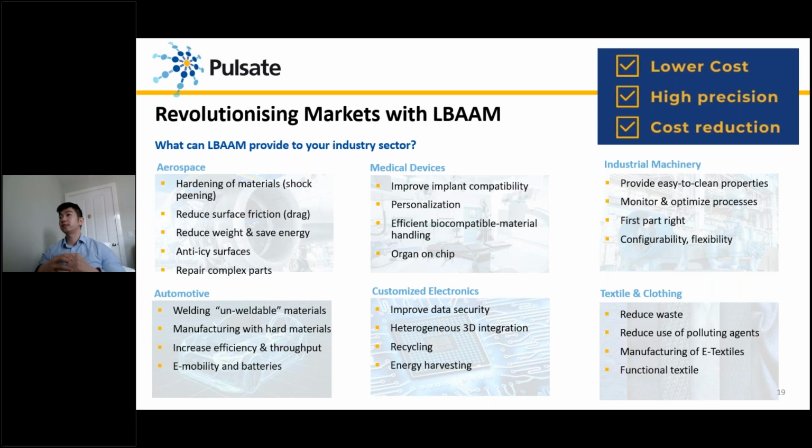So generally speaking, lasers can be used for either addition of materials or removal of materials. Those are the two main big categories. And under those two categories, you can go down to different processes. For example, for laser removal, you have cutting, drilling, texturing, laser cleaning, and for materials addition, you will have laser cladding or direct energy deposition, as some people prefer to call it.